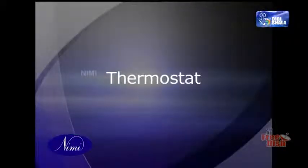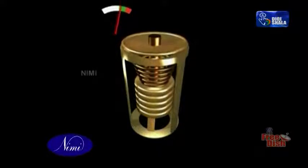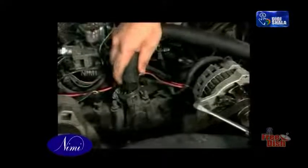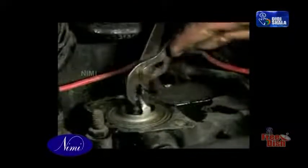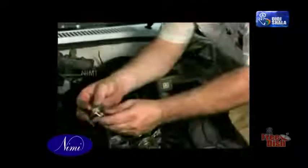Thermostat. This is a heat-sensitive valve that controls the water temperature by altering the speed of circulation. It is generally fitted on the engine side of the top hose and is preset to stop the water flow to the radiator when the coolant temperature is less than 80 degrees Celsius.